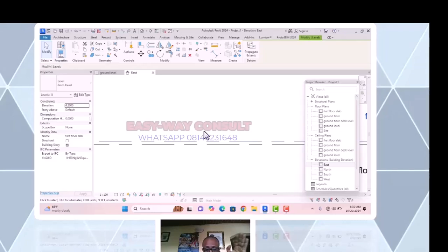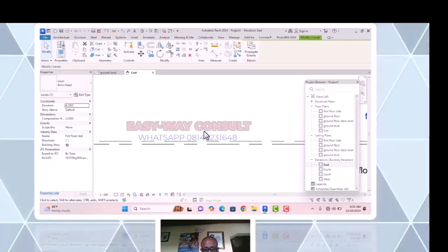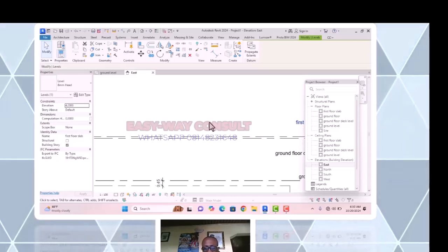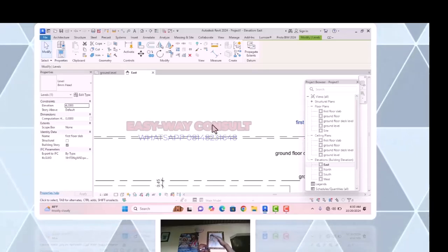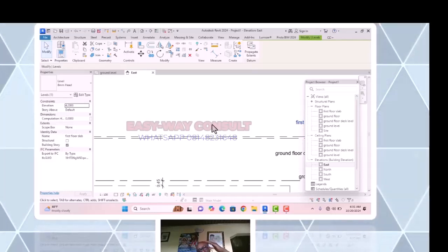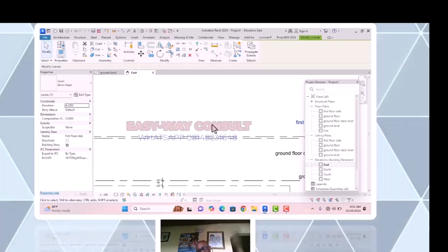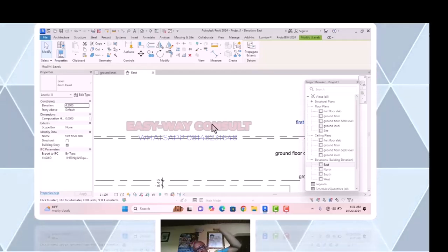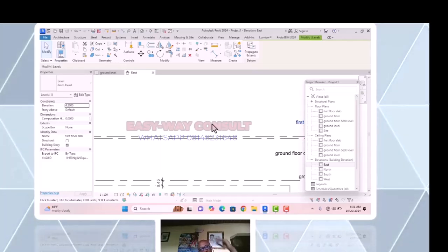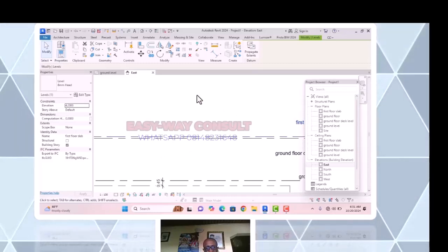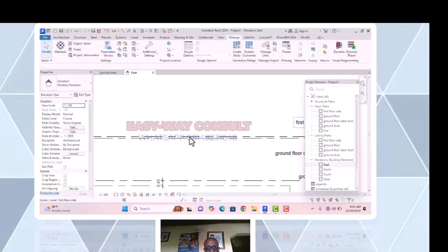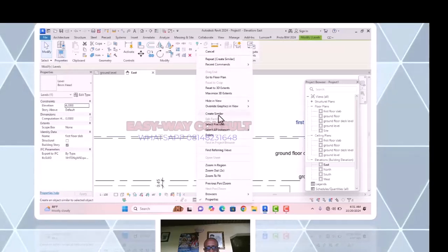When you get to the last floor, if we're having another deck, it means I'm going to make it 3.6 again. Why we are doing it is for us to be able to get that 300 height that we need. Except if you're not going to use ceiling or POP on your deck, you just have to paint and design the deck. But if you want to use POP or ceiling on your deck, you need the space to do that. So we are going to offset this to 300. You click on it, create similar again.